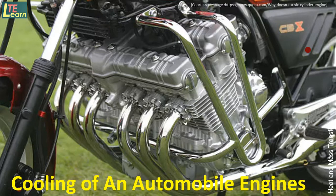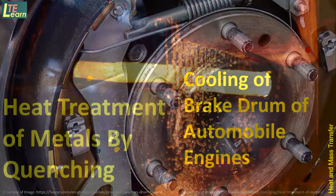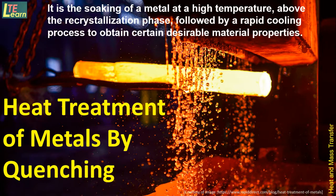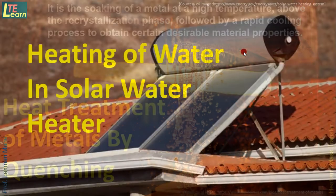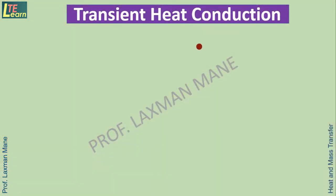Cooling of automobile engines. Cooling of brake drum of automobile engines. Heat treatment of metals by quenching. It is the process of soaking a metal at a high temperature above the recrystallization phase, followed by a rapid cooling process to obtain certain desirable material properties. And heating of water in a solar water heater. In all these examples, the process of heat conduction that takes place is transient heat conduction.